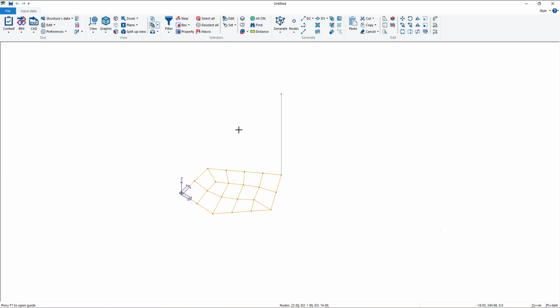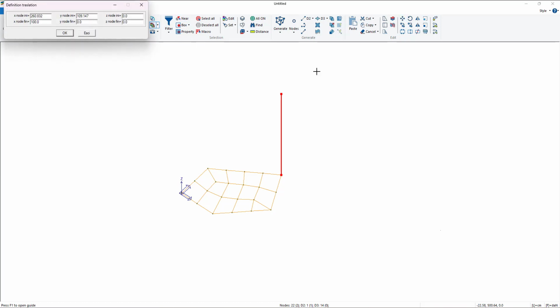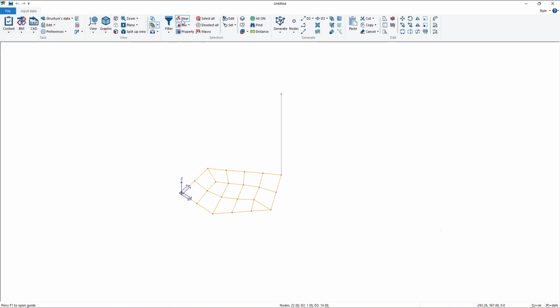What are we missing there? Okay, we can talk about edit commands. Well, they're very simple. I can click an element, and with move you can just move it. So there are some different ways to do that. Let's say that I want to move it from there to there. First of all, I should not select this node, because if I move this node, the topological definition of the D3 element is gonna give me an error. So I'm just selecting these two elements, move.